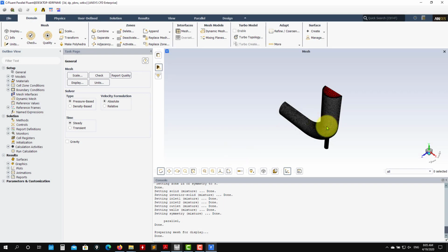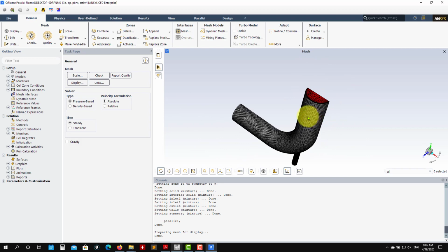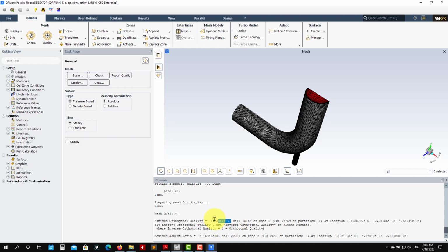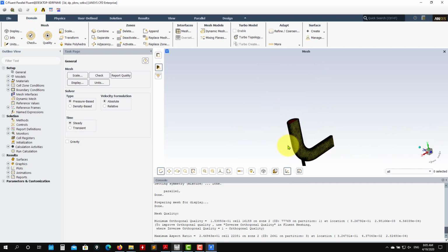Okay, in my case, Fluent is already open. See that you have your mesh, beautiful mesh. Remember, first thing, always check the mesh quality. Okay, see that it is okay. Here probably this value is perfect. Probably at 0.01 you can start to worry about the mesh, but usually if you follow good standard practices, you will get good quality meshes.